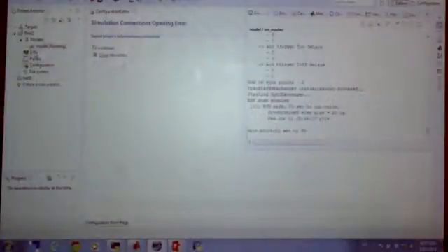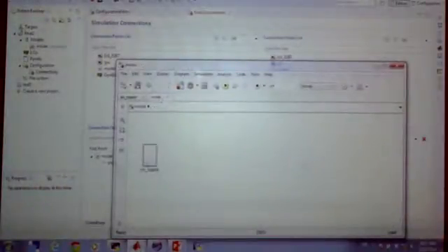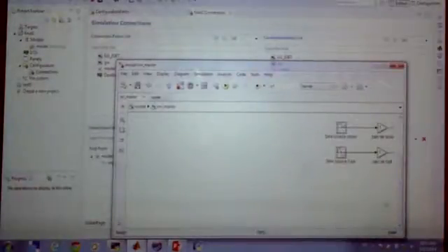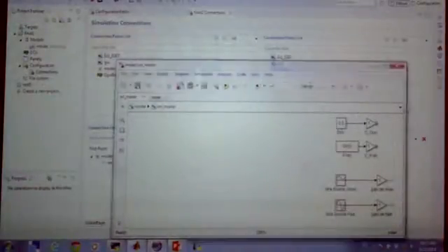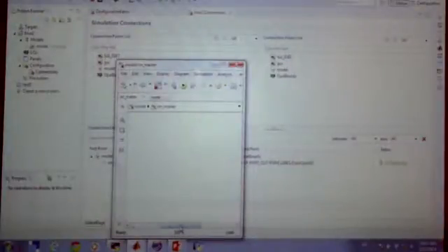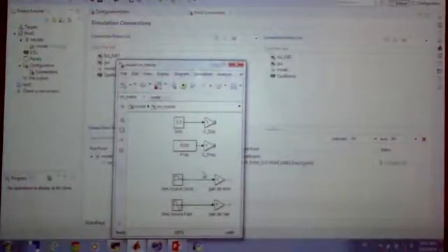And what we have done here, so we saw that there is a mapping and connection system in RT Lab. So if we look here, we actually connected a model. So for example, if we look at the Simulink model that is almost empty, let me just move it here. So that's our model. It's actually an empty model. I don't have anything inside this model except a few sources. So if you see on the top, I have a duty cycle, which is basically a constant block. I have two sine waves, one that is a slow sine wave and one that is a fast sine wave. So really, really simple, the most basic model that we can have.